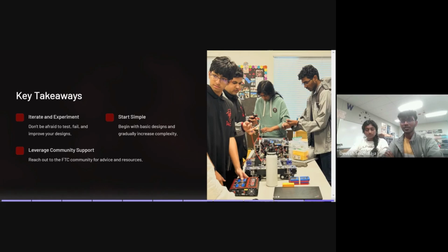But I do completely recommend using color sensors to intake blocks from the submersible because they can give you really useful driver feedback. If you're positioned in a spot where you can only see the pillar of the submersible, but you want to know what block you received, you can configure it such that when you get the right block, your controller starts vibrating, your latch mechanism on your intake seals up, and your robot automatically transfers. Using these sensors allows you to automate most of your autonomous processes, which increases efficiency during the game. Thank you.